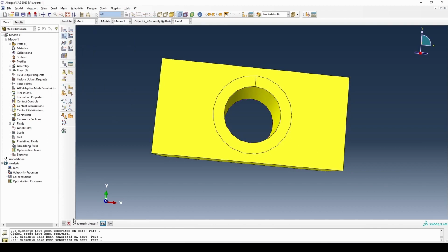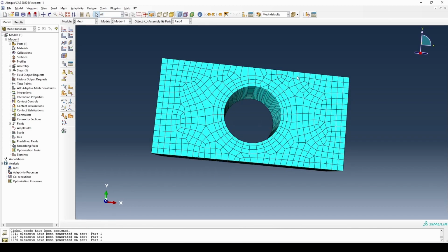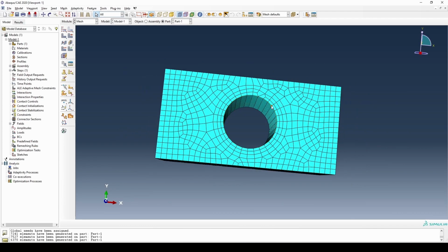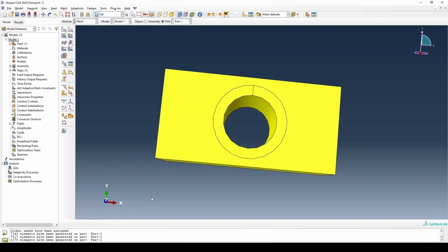We will remesh the part to evaluate the mesh. We notice that Abaqus did not always respect the 3 elements between the two circles. To solve this issue, we will create a surface partition using the same technique as before and add 2 edges to guide the mesh.